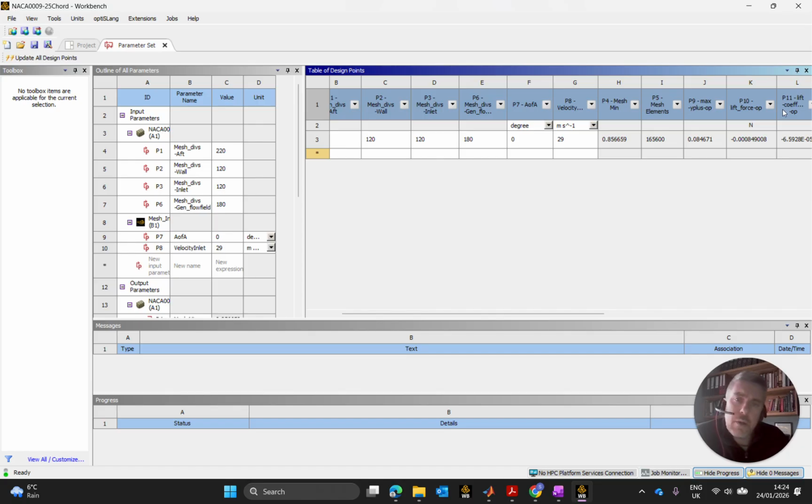And then there are also output variables here that I care very little about looking at. What I want to take out of this, I'm going to look at 3 variables: the lift coefficient, the pressure coefficient, and the drag coefficient. Okay, so the 3 coefficients I'm going to look at. Everything else there I can take away. I will keep y plus on as well, just to validate that as I make a coarser mesh, which I normally wouldn't do. All right, very important to know that.